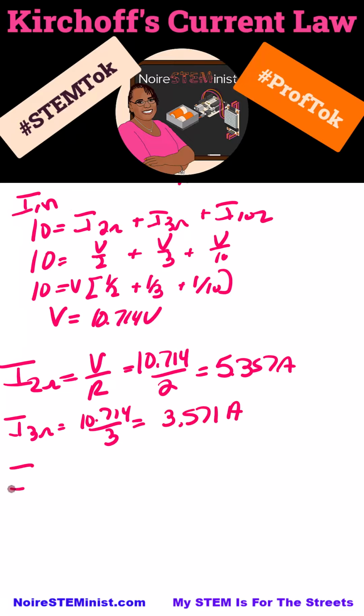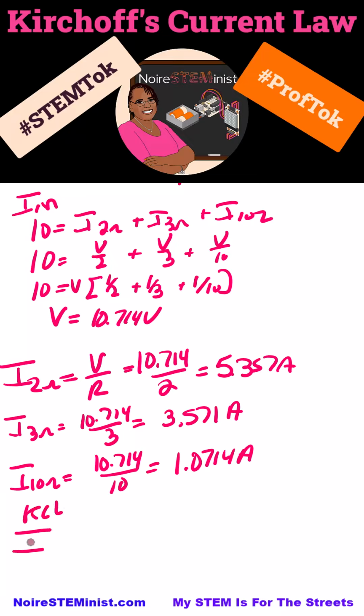And the current through the 10 ohm resistor is 10.714 divided by 10, which is 1.0714 amps. And because of KCL, I know that the current from the source has to equal the current through the 2 ohm plus the current through the 3 ohm plus the current through the 10 ohm. So when I add those all up, it has to add back up to 10 amps.